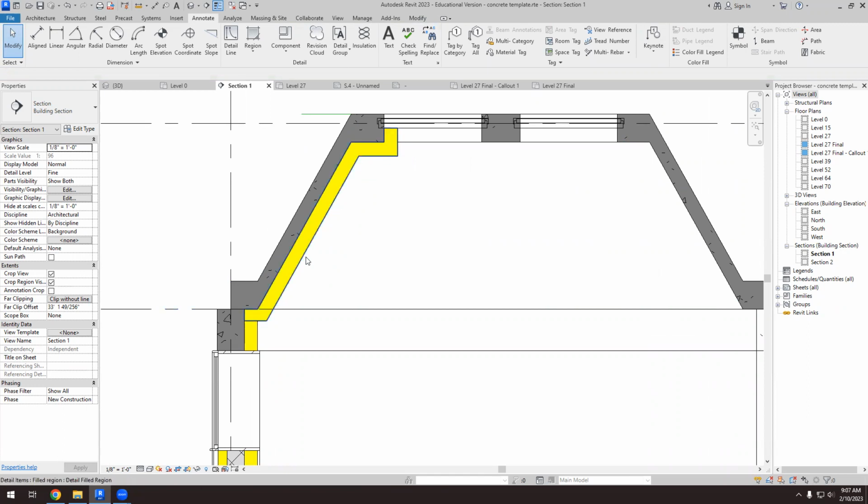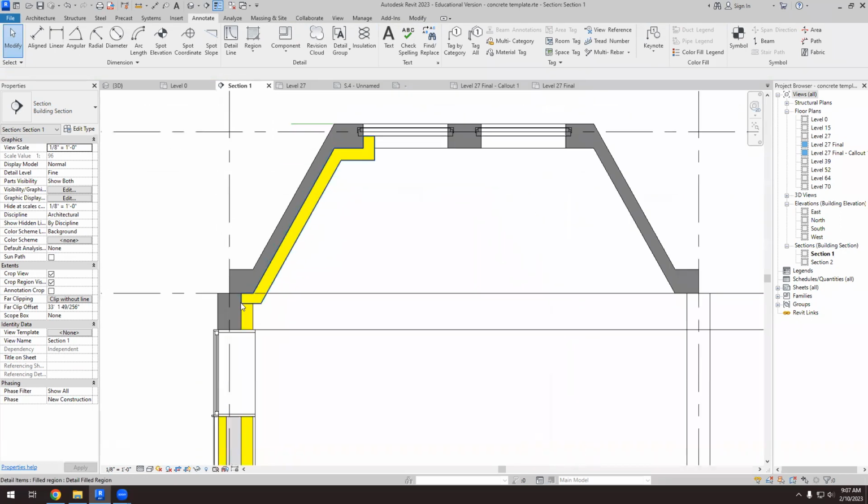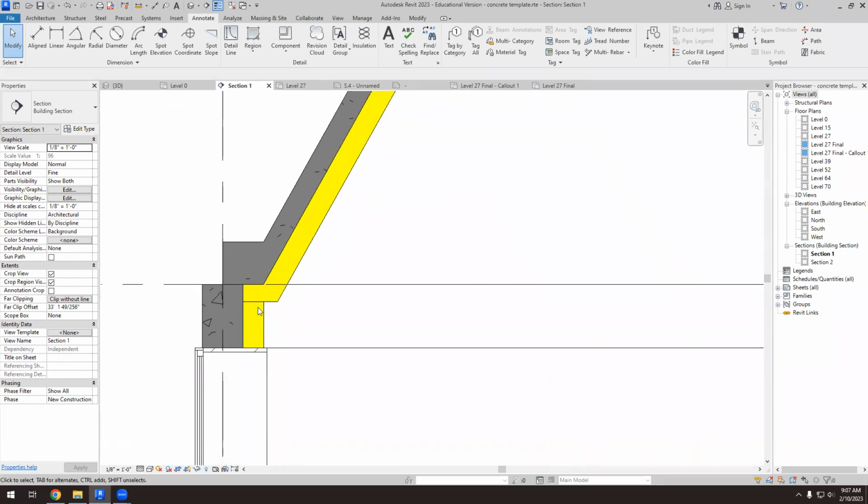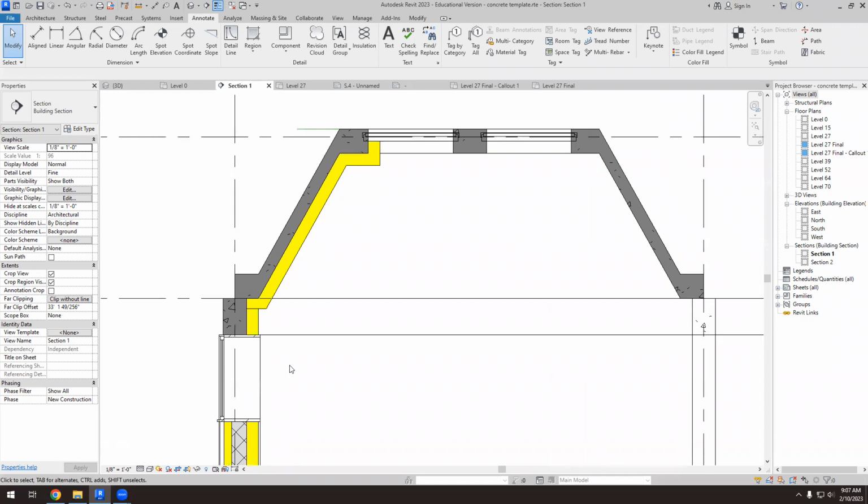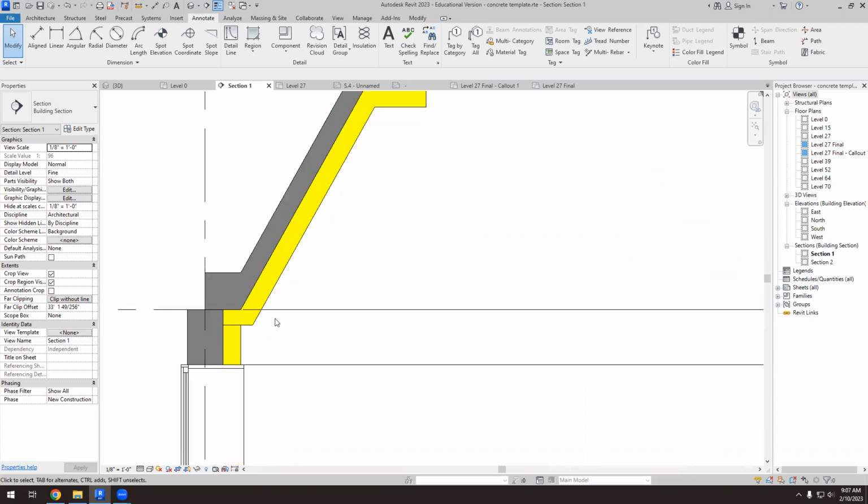we don't interrupt the thermal insulation. Well, we do interrupt thermal insulation because we have a window, but well, we need windows. But interrupting the thermal insulation in a solid wall, we don't do it. So we solve that issue with the thermal bridge. But this is the thermal insulation, and we need a finish.